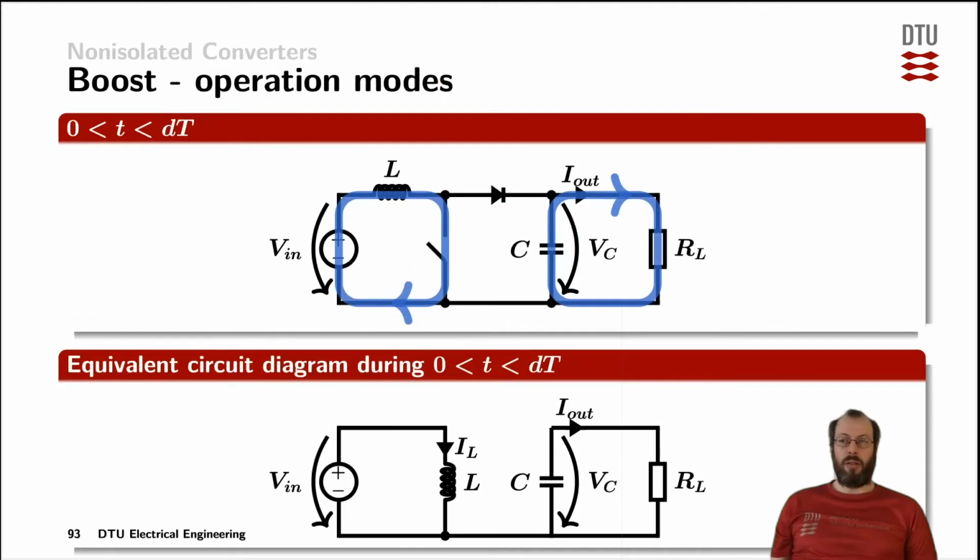When the switch is turned on, the right-hand side of the inductor is forced to ground through an ideally perfect short circuit from the switch, and the current can return back to the source through the ground wire. During this moment, the inductor is getting magnetized. As the switching node here is pulled down to ground, the diode is in reverse bias and is a cut-off of the circuit. Therefore, it's the capacitor's responsibility to supply the load with its necessary charges to generate the output current, which we can see up here.